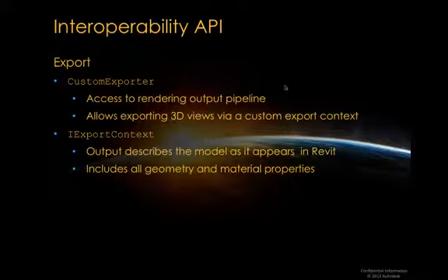In the IExportContext interface, you receive the output describing the model just as it appears in Revit, including all of the geometrical and material properties.